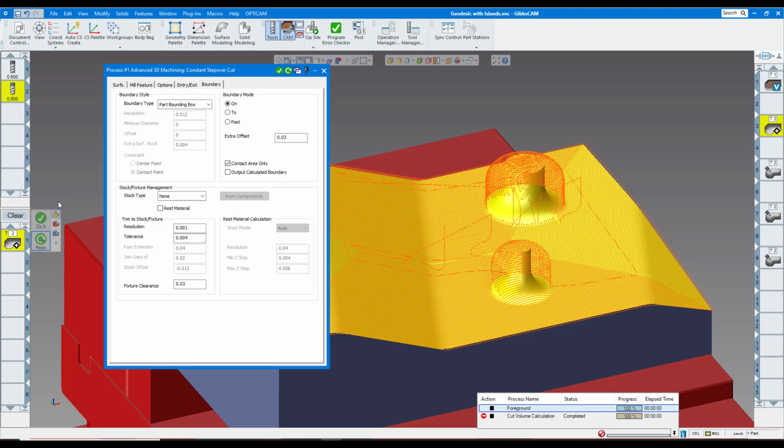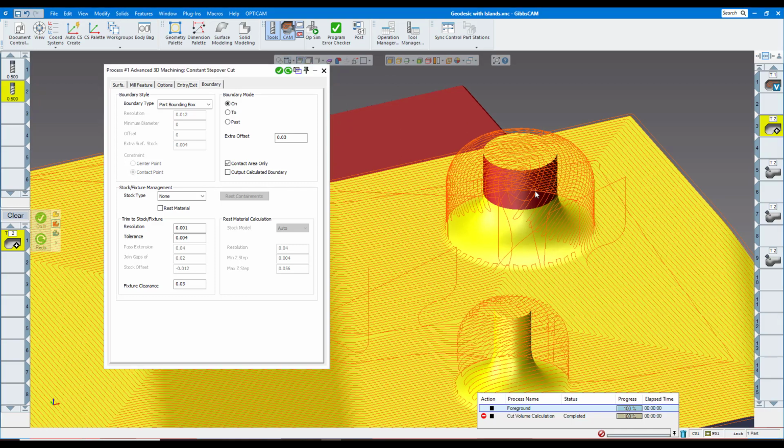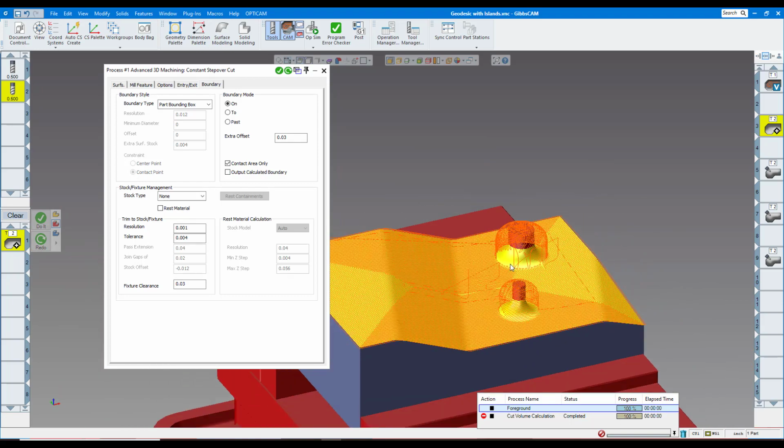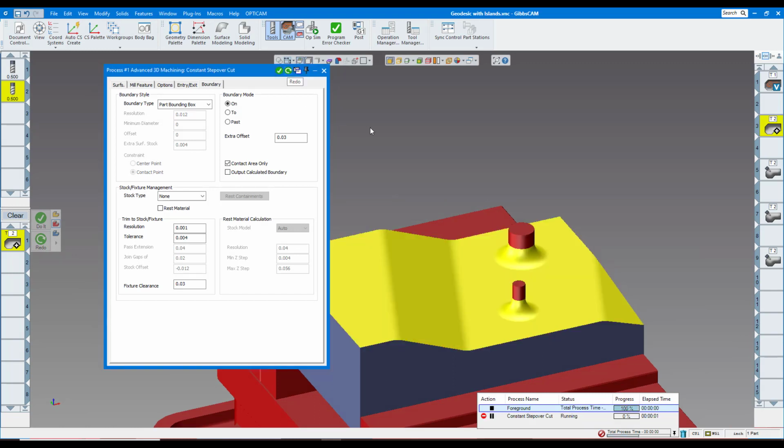So I'm going to turn that off, the notes there. I'm going to click on that, make sure face selection is on. And I'm going to say I want to make this a constraint as well as that, and this as well as that. No need to do it here because the end mill is going to leave material on these 2, which will leave material on the radiuses as well. So I'm going to click on redo, and you can see the toolpath calculating right here. And now we have our toolpath, and you can see it's staying away from those islands.